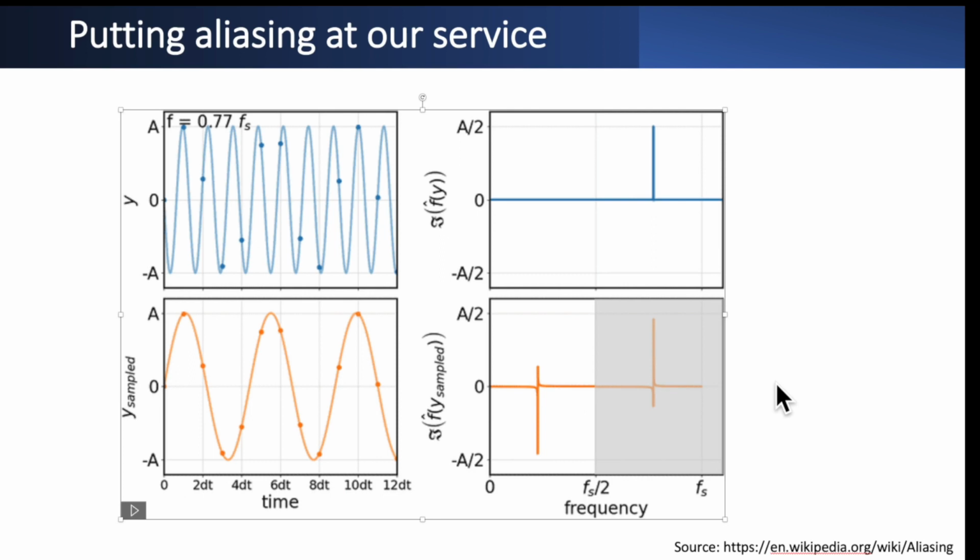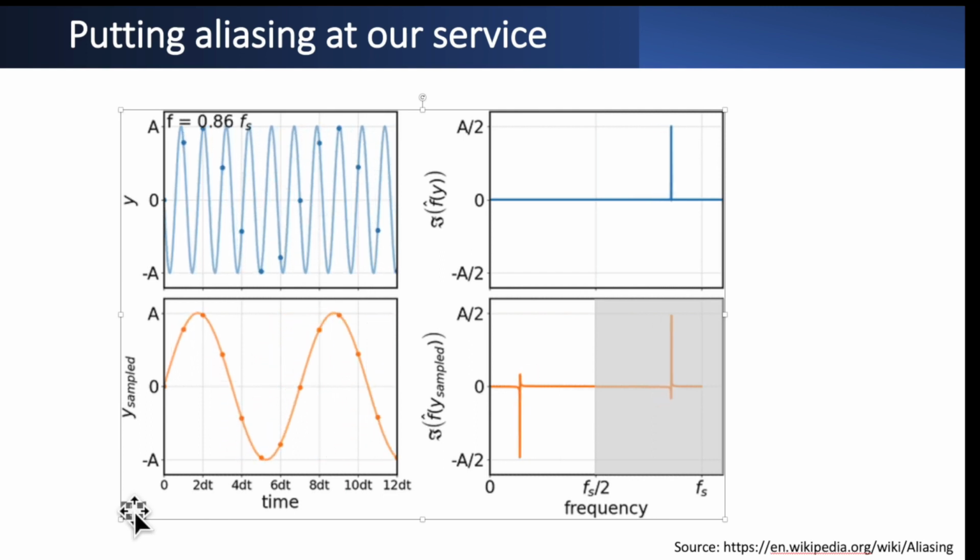So what has happened basically? The input frequency here is above the Nyquist frequency. Again we see the sampled points that we got, and we see them down here as well. But if we don't know the original waveform and we just have these dots, the sampled values, we can just as well reconstruct the orange wave that we see down here. This wave doesn't really exist, of course, but that is what we will be able to reconstruct if we offer a signal that is higher than the Nyquist frequency, which we would normally not like to do. And so that's why we get this value here, which is going further down if we further increase the frequency.